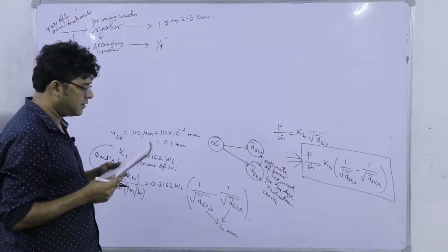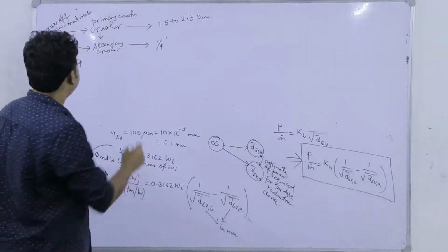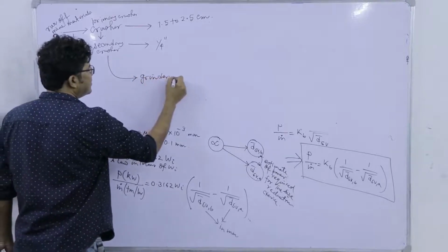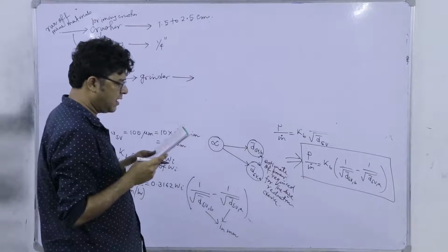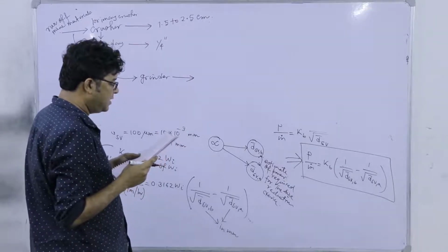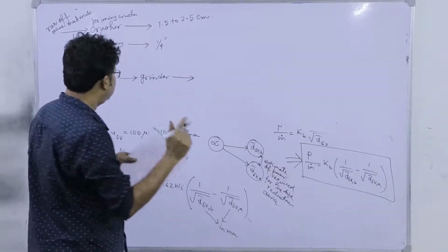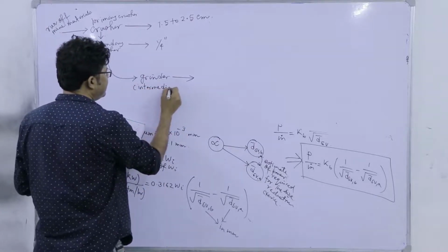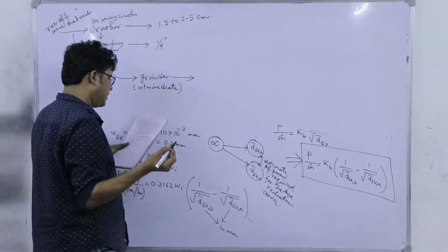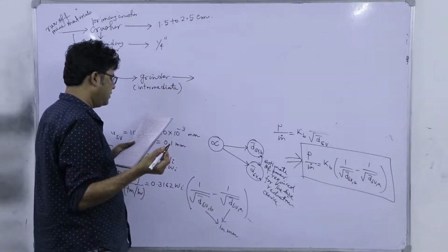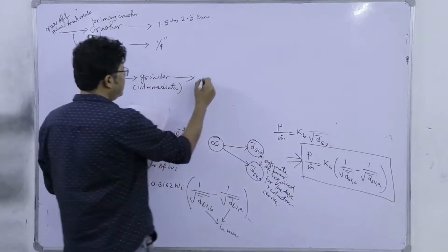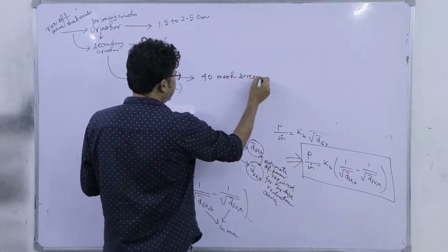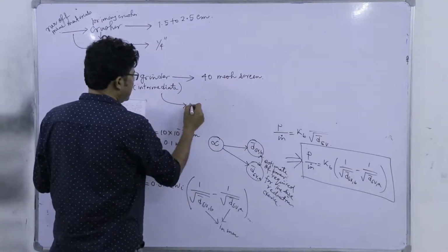So, a grinder reduces the crushed feed to powder. So, this is the feed to a grinder. It produces a size, the product from an intermediate grinder. It reduces to a size around this 40 mesh screen. Most of the product passes 40 mesh, and from the grinder it goes to the ultra fine grinder.